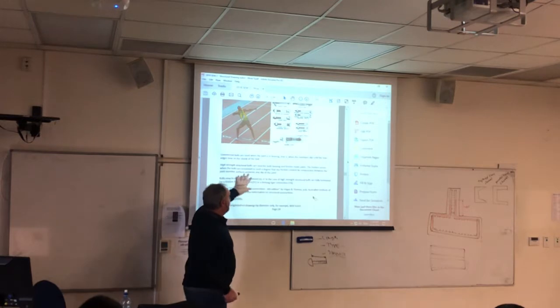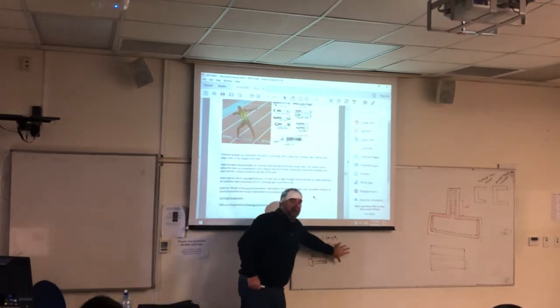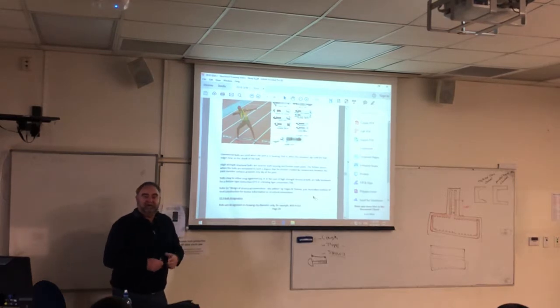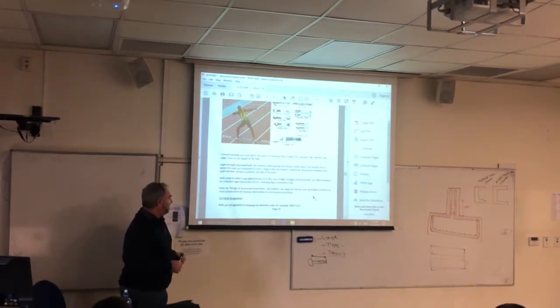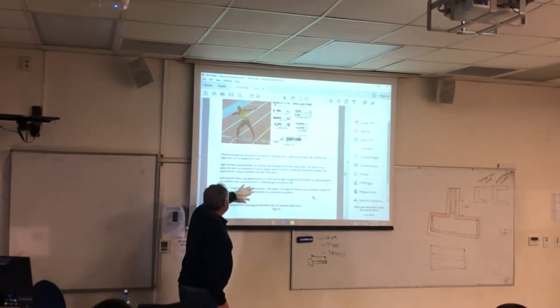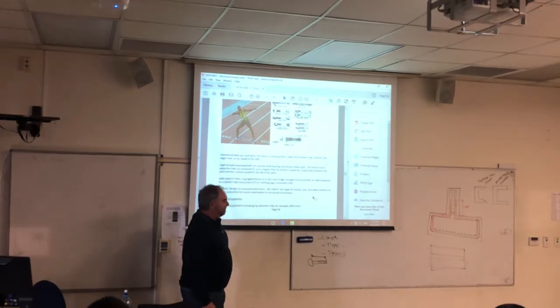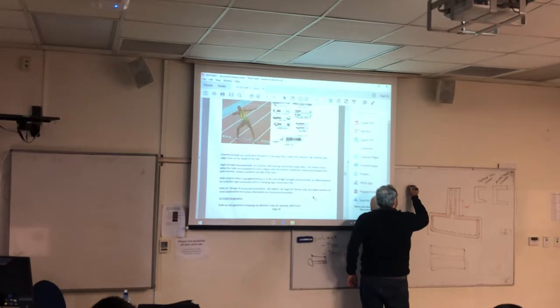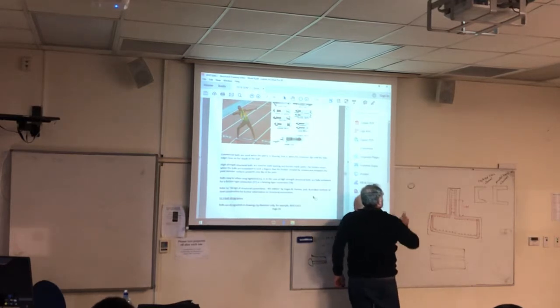You don't have to worry about this when you call it up for the drawings, but in terms of general knowledge, I'm covering these things as I'm going along because this is another great little section for a multi-choice question. And it's to do with the snug fit and the friction fit type joint. So your snug fit joint is always going to be a bolt in a hole which is 1 millimetre either side, right the way around.